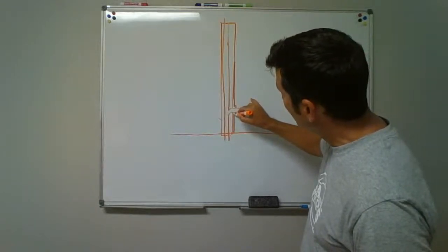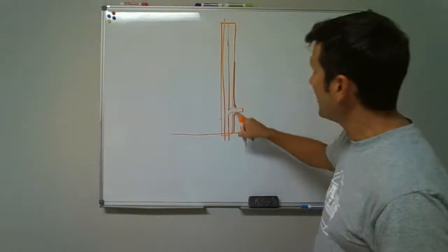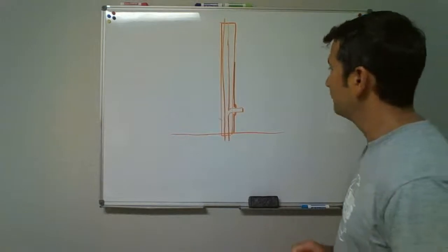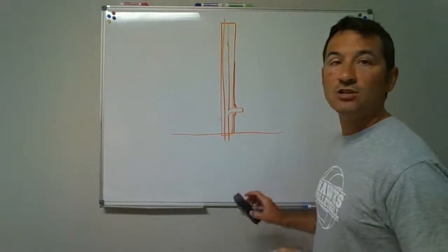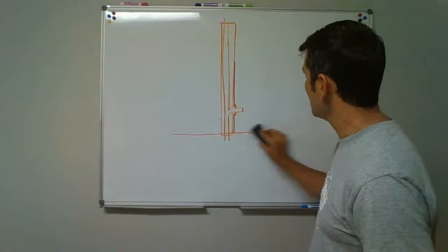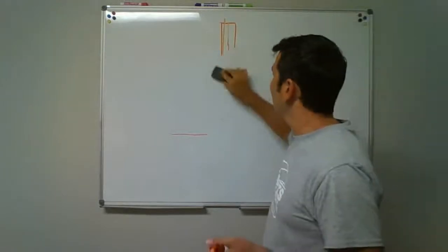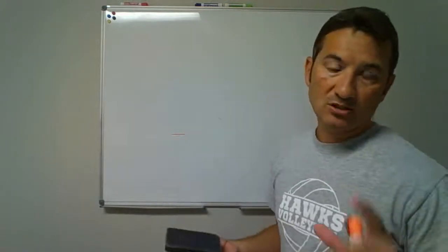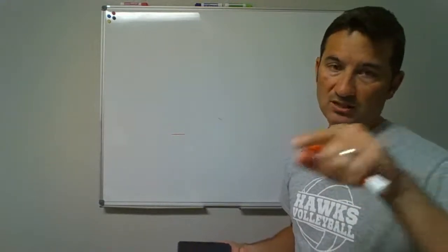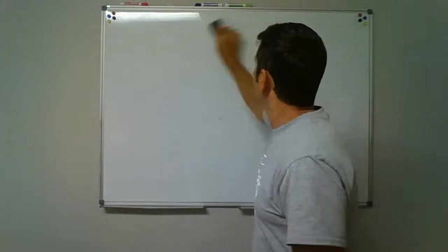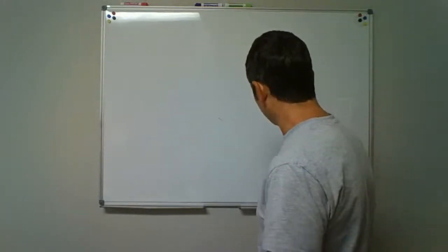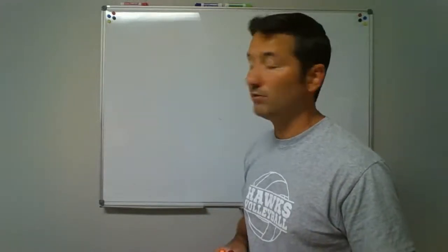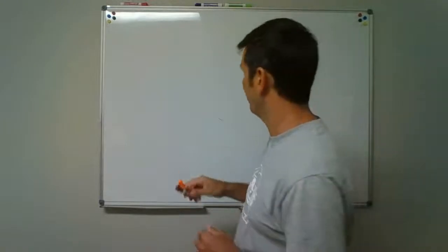The trim ring is going to go around the pipe, and it's going to fill that gap. We've got to have all those gaps around the pipe filled off and closed off, and that falls under rodent proofing. So they'll get you on the final for that. If you say, hey, we're done, we're ready, and they open up your cabinets and you've got holes exposed around your pipes to where they can see back into the wall, they'll more than likely turn you down and cite code 304.4, saying you need some rodent proofing there.